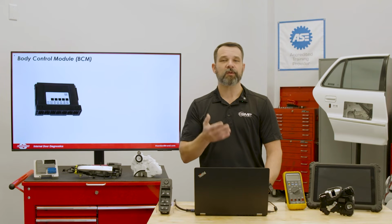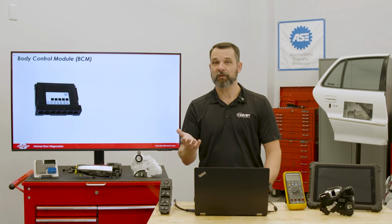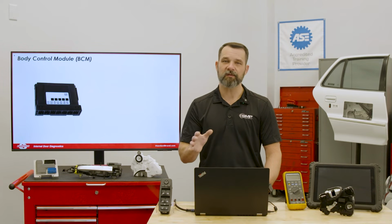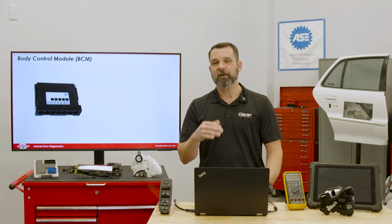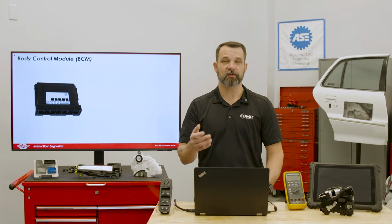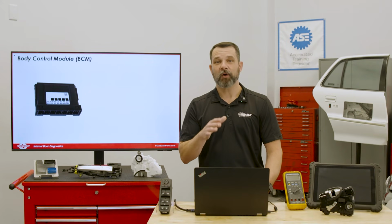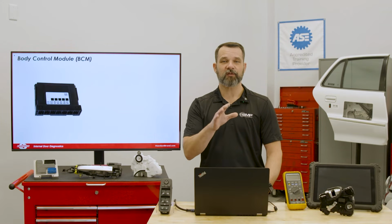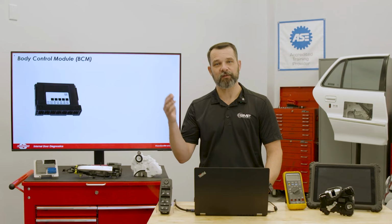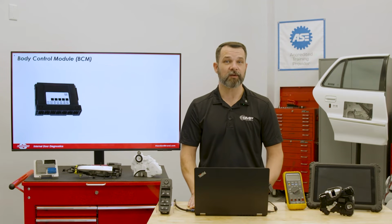And so things like door lock commands, keyless entry, security systems, window auto functions, interior lights, all of these are going to be coordinated through that BCM. And the BCM is also going to monitor circuit faults. So for example, if the BCM detects an overcurrent window motor, or an actuator with too much resistance, it can actually disable the output and store that DTC for a later review by a technician that may be working on a trouble code that's coming into their bay.